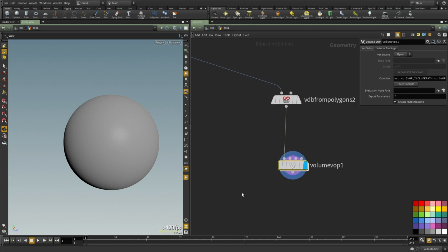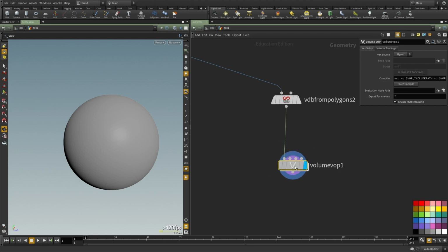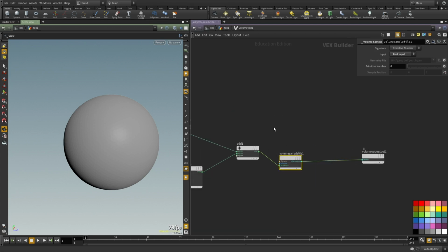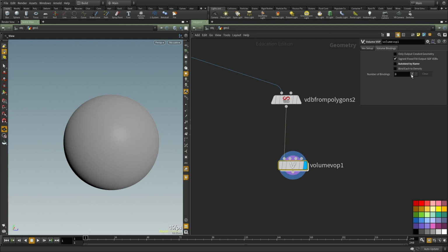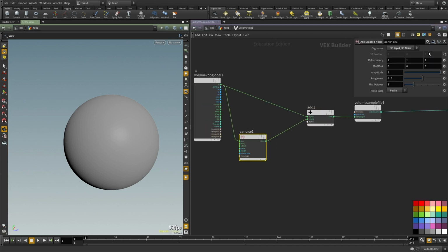Well, nothing happens. Now why is that? Well, if you middle click, it says surface. Here it says surface, it doesn't say density. Now we saw that we can remap, do custom binding for the data. What we can do is come in here and untick auto bind and create a new binding for the primitive density, and we're going to call it surface. And by doing that, we should be able to see